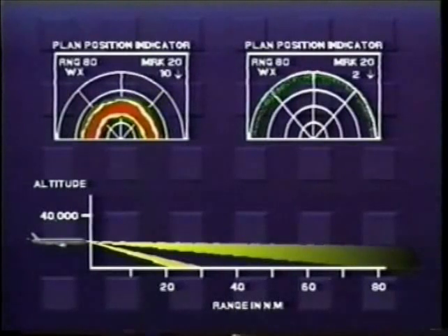Around 20,000 feet, switch to the 80 nautical mile display range and set the antenna tilt controls to 10 degrees down. Slowly rotate the antenna tilt control up while watching for weather cells until ground is being only lightly painted on the outer edge of the displayed range. As the climb proceeds, continue to make small adjustments to the tilt as necessary until the aircraft reaches cruise altitude. This procedure will correctly point the antenna beam and create a zone where no storms can go undetected.